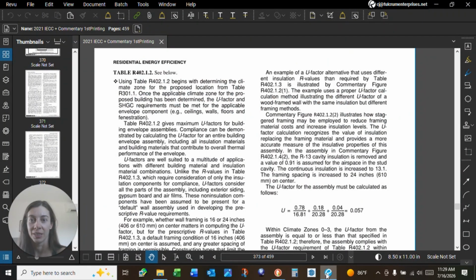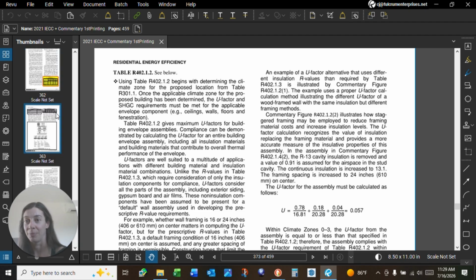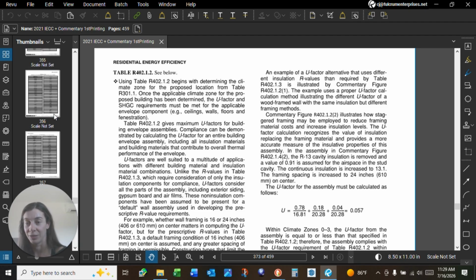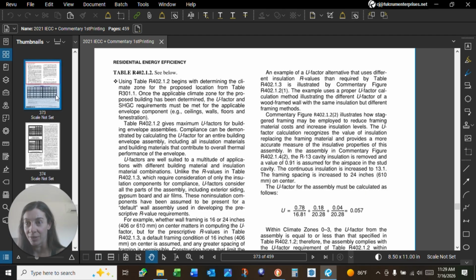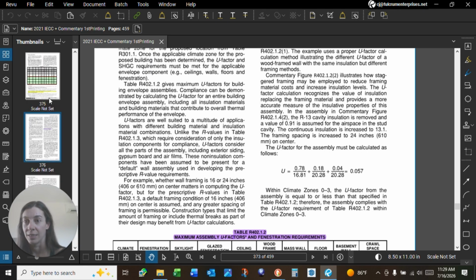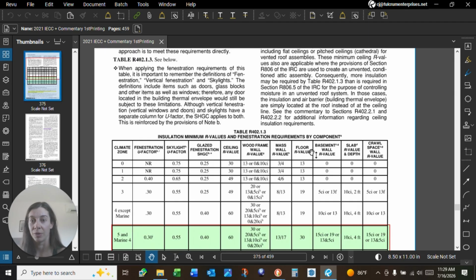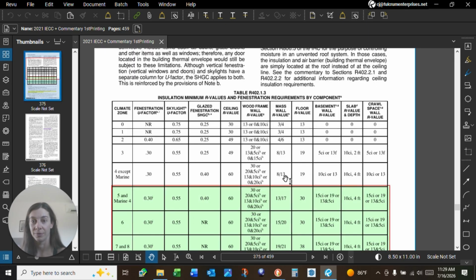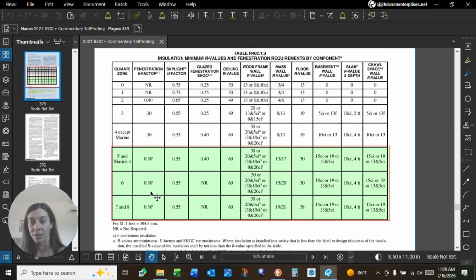All right, we're going to touch real quick on energy code pathways of the IECC. So you have the prescriptive route or the performance route. Your prescriptive is literally by the table, and I'll just show you real quick the tables, because this is honestly the most common route, simply because people can look at the table and just be, hey, cool, I'm going to install that. Okay, it's based on your climate zone.